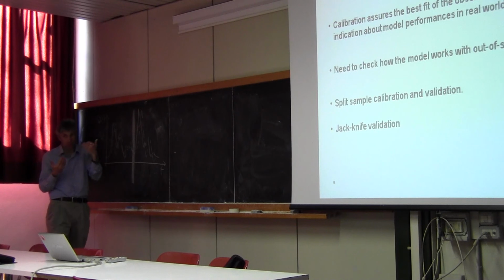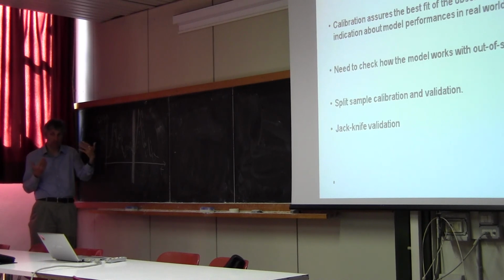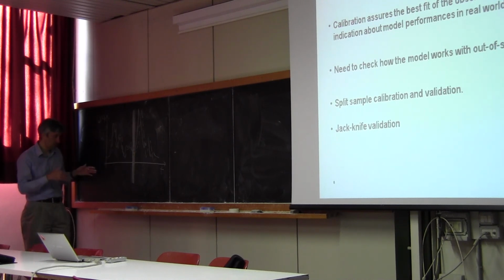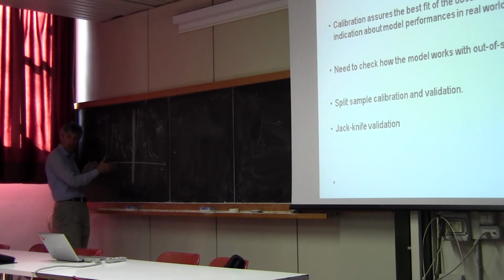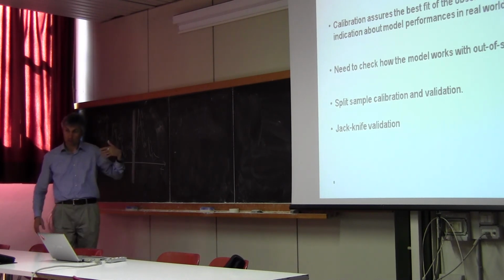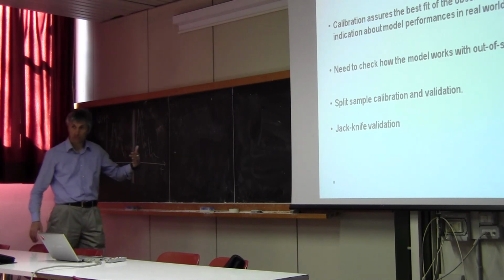If you want to perform generation of synthetic data, I think the validation period should be at least 1 year, because if you generate just one data point, it's not really a long enough validation. But once you get a sufficiently long period for validation, you can move this validation period inside the hydrograph by repeatedly performing validation.